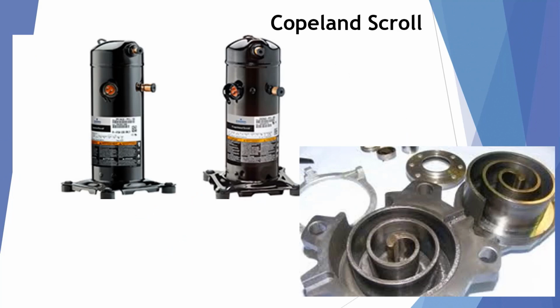When the Copeland scroll hit the market, one of the marketing ads was that they could pump liquid. And it is true that the orbiters on the scroll compressor are less susceptible to liquid slugging damage than the reed valves on the piston type compressor. But scroll compressors can be damaged by liquid slugging also. And so it is very important to maintain superheat into a scroll compressor just as it would be on any other type.